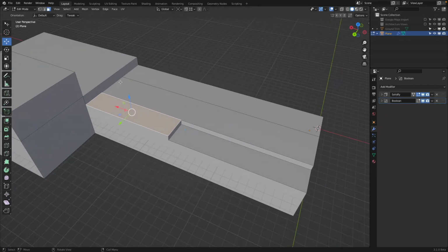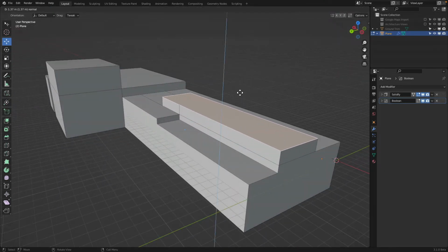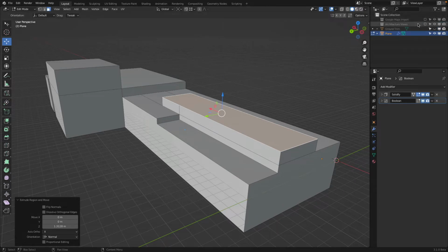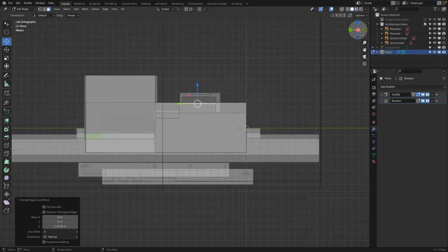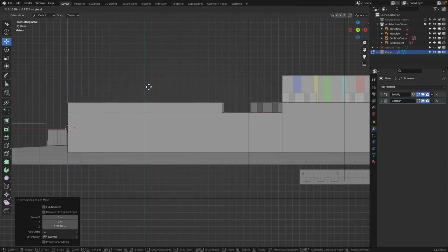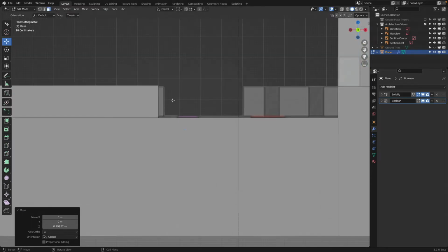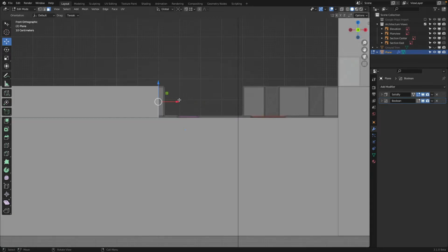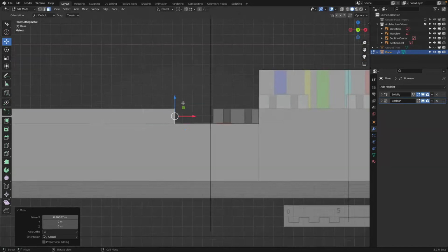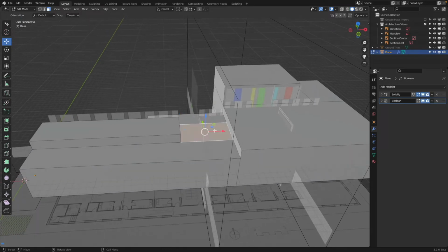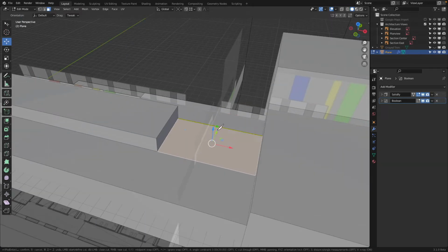Okay. So same tool again. K, click, and then this is in this case Y, click and enter. Then I can select this face, E, and this goes up. How much? Let's turn this on, side view, there till there. I can also see here that this should be roughly there. Very good. Now here comes another piece that goes up. So K, click Y and click and then enter.